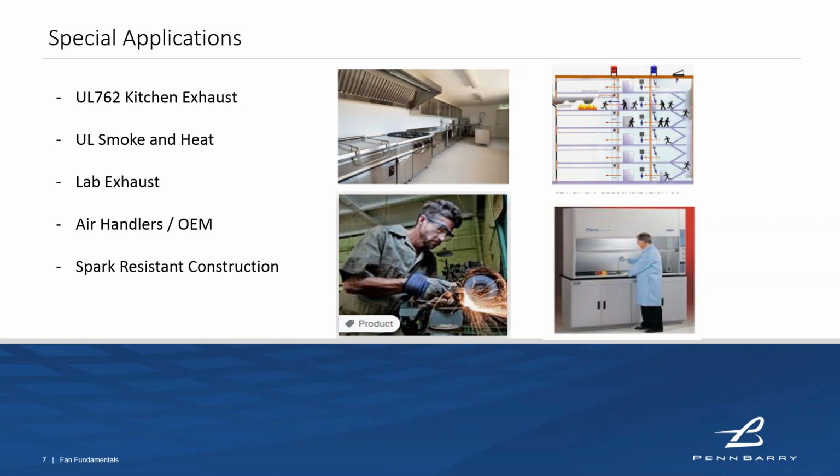If you have a fan that's made entirely out of aluminum, it's going to be a really poor choice for a smoke and heat exhaust fan. So we are kind of driving into a situation where, if you need this, you're constraining the type of product you can have into housed fans that are made of steel.